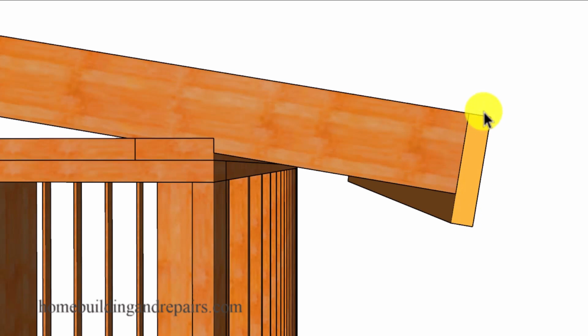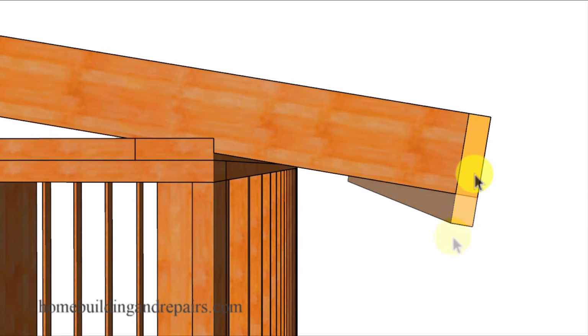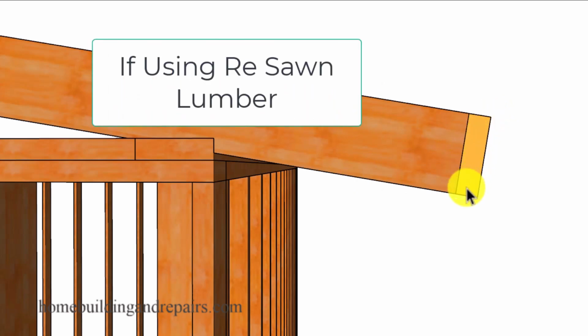You're simply going to use fascia board that is a little bit larger than the roof rafter. 2x6, 2x8. You have a 2x4, maybe you're going to have a 2x6. Or you can have a 2x6 roof rafter and a 2x6 piece of fascia board. However, this usually isn't that common. And the reason for that is some fascia board is actually a little smaller than the roof rafters. For example, if I have a 2x6 that is 5.5 inches wide, I might have a piece of 2x6 fascia board that is 5.25 inches wide.